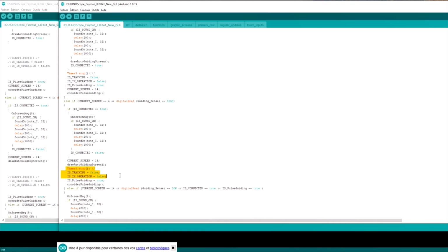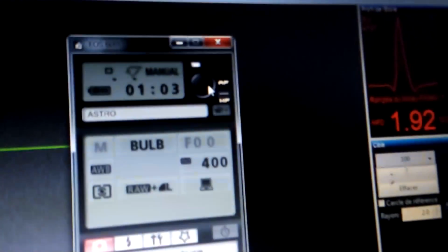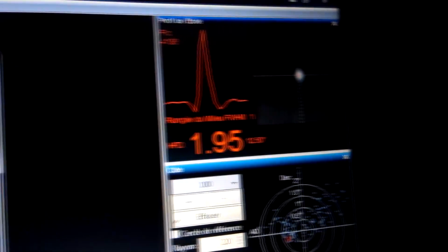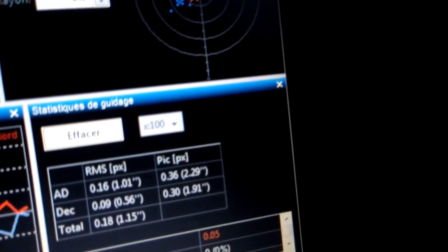At this time I'm not sure the Autoguiding is working perfectly because my setup wasn't very robust. Maybe I have to revise the code because for the RA axis I'm not sure that adding plus pulses or RA minus pulses will correct the periodic error. Increasing or decreasing the speed will be better. At this moment it's uncertain, but it may be settled before the end of the tutorial.